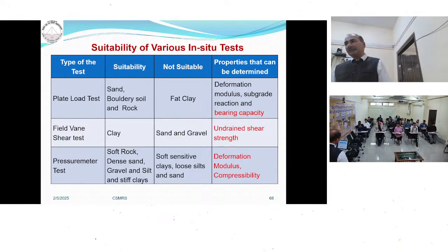But the only limitation of this test is that the results are valid up to twice the width of that plate. If you are using a 1 by 1 meter plate, then the results are valid up to 2 meter depth.